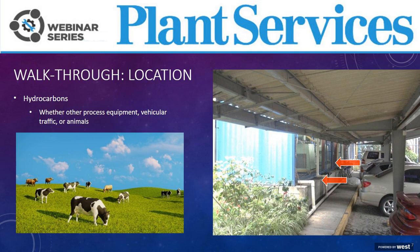Note that if your facility is near a pasture, you may not have a choice in how the wind blows or the quality of the air ingested by your equipment, so you want to take this in mind during your design phase. In some cases, like we're seeing at the facility at the right, you may not have room within your plant for your compressed air equipment. So, note here is that installing industrial equipment outdoors isn't recommended. However, there are options, such as package systems with full enclosures that could be offered to protect your equipment from the elements.